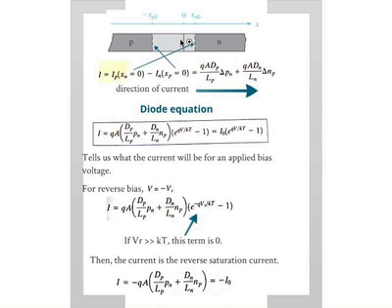So if you calculate them independently and add them up, you get the total current at any point along the bar. Again, remember the assumption is that the current is constant throughout the bar. There is no potential drop through the neutral regions of the bar. That should be pretty obvious.